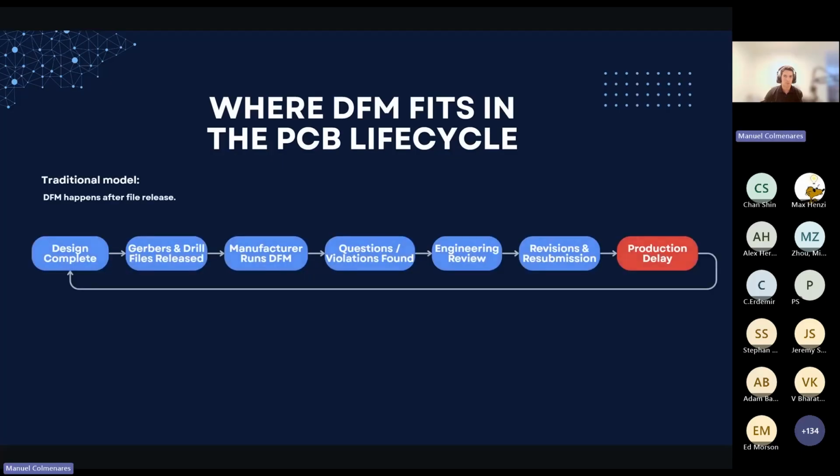So traditionally, where does DFM fit in the PCB lifecycle? Traditionally, the designer finishes the design and exports the Gerber and drill files. It then gets to the factory, and the manufacturer runs the DFM, and then the EQs start going back and forth. You have questions, some violations are found, and the engineering team has to make changes and accept changes, back and forth, creating a bunch of delays. It's a cycle that can go over and over again until it's fixed.